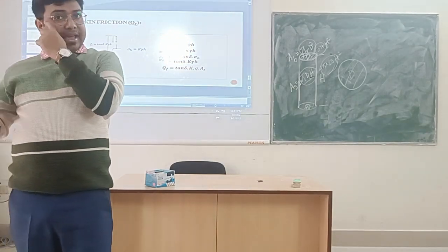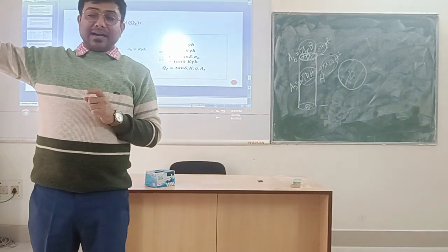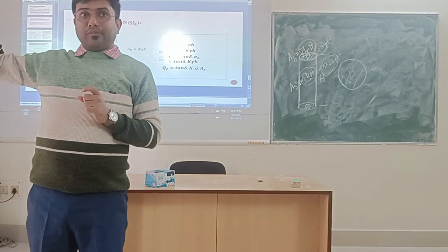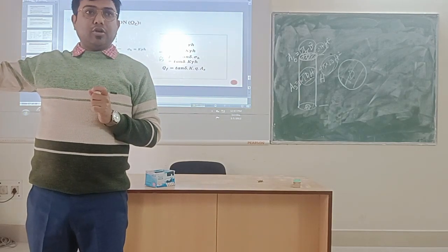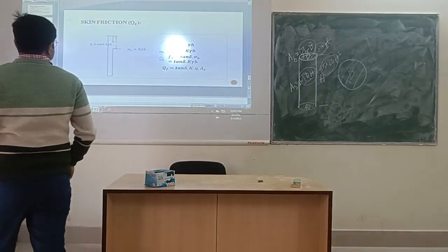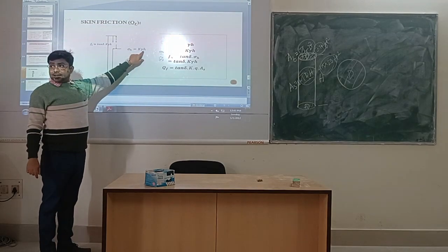The formula is K gamma h and Kp gamma h in the lateral earth pressure theory. That is the Rankine's earth pressure theory. Have you all forgotten those concepts of earth pressure? That was the first module of the soil mechanics 2.